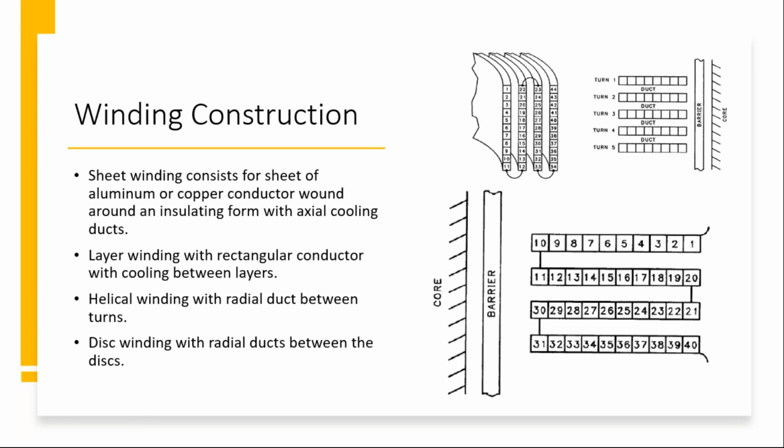So the pictures here represent how the windings are manufactured. Winding actually uses a copper conductor, which is paper insulated for oil-filled transformers, or it could be aluminum for small-rated transformers, depending on the customer's choice also. So these are the four types of winding which will be utilized.